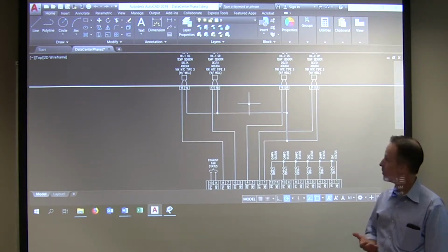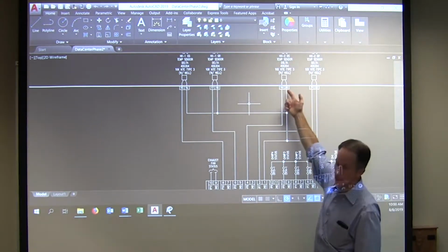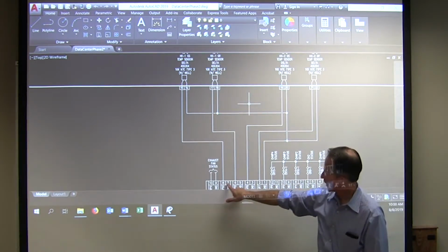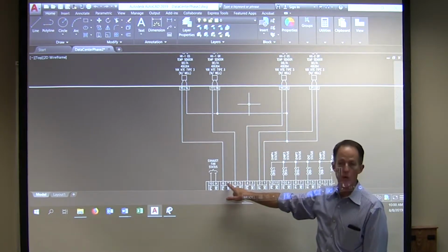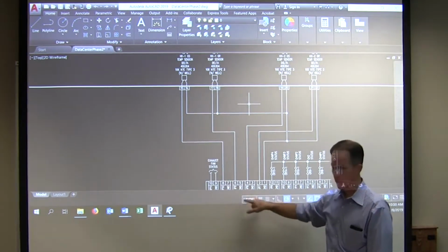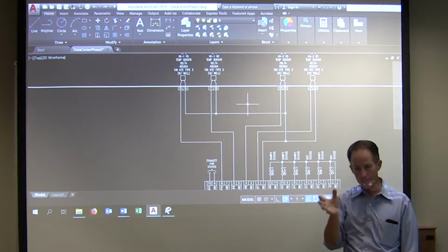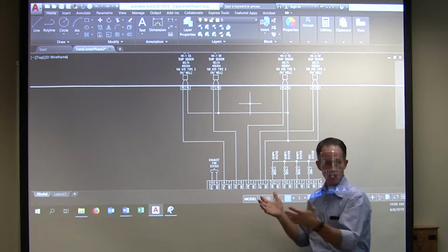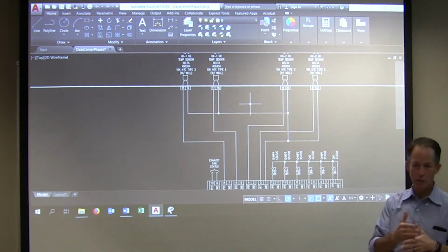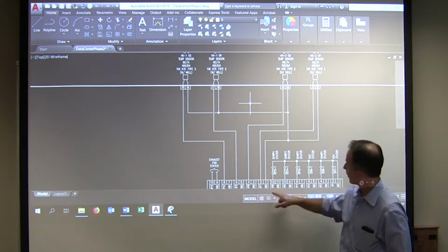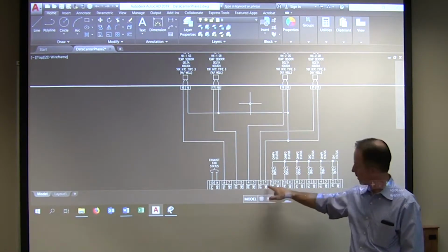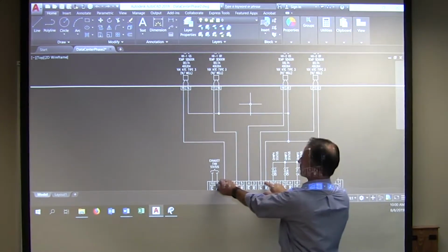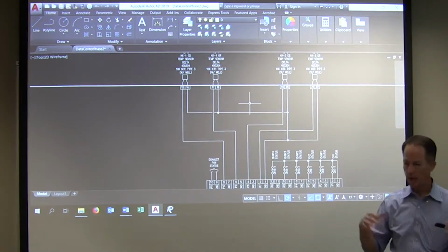On the ground. Okay, so there's a couple different places. I could try it here, but again, we're trying to get back to the controller, right? So I'm going to find where there's a ground. Now there's a ground here, but there's no wire. Can I use that one? Usually you can, because internally the grounds are all tied together. Now, there are some controllers where that doesn't work. If you're not sure, go ground to ground and see. If you do continuity, you should get the tone and it should work. But I can always come where my ground comes into this one. I can put one side of my meter here, the other side of the meter to that wire, and I check it. Everything's good.